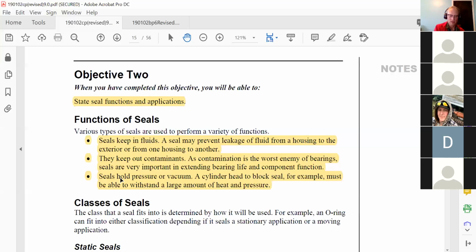That's used to be what it is. Drive axles, transmissions too. Your transmission sometimes might not have an express vent on it, but manual transmissions, the top of them aren't sealed, like where your gear selecting lever bolts onto the transmission. Pressure can leak out from there as well. And drive axles too, there's a breather or a vent on the top of those. But if all that gets plugged and pressure starts building up, those seals won't hold the pressure.